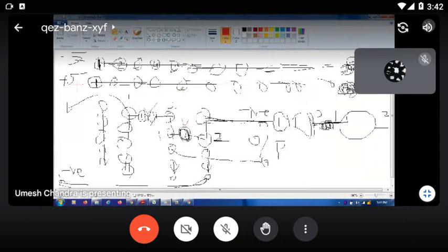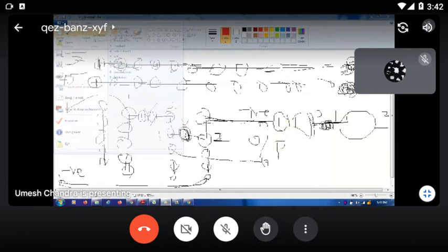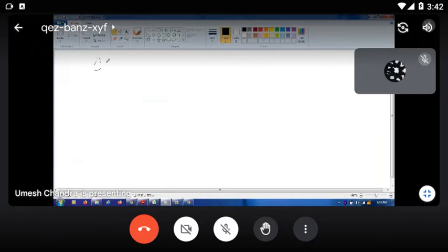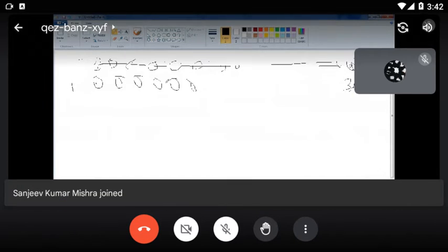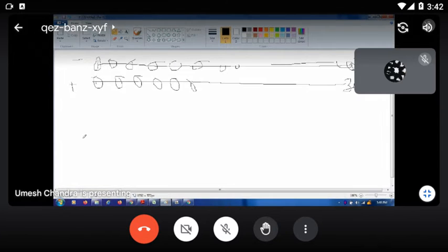And this is the holes, it is 30 holes, up to 30. When you give the negative voltage to pin number 1, then you get the same negative voltage at pin number 30. Okay, that is internally connected. And when you give the positive voltage to pin number 1, then you get the same positive voltage at pin number 30, that is internally connected, horizontally internally connected. And vertically, that's 4 holes like this.